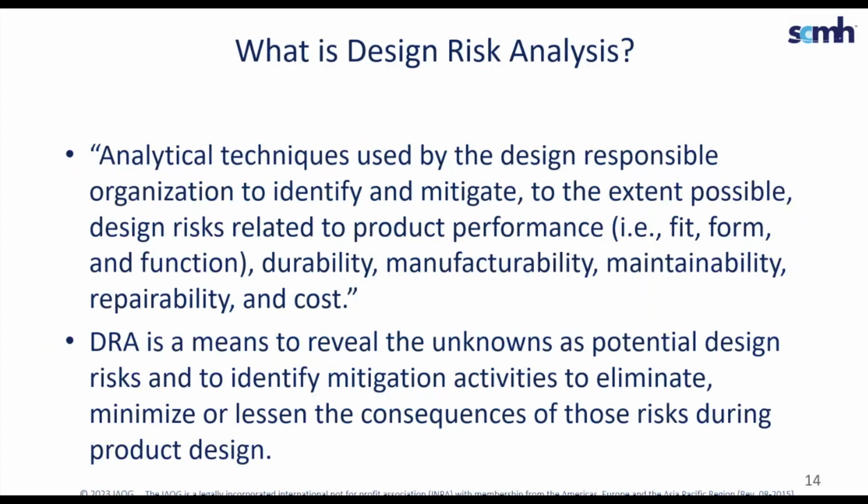Now, I do want to note that the aerospace safety assessment process, and you can reference ARP 4761, is an independent process from DRA. However, the safety assessment process does interact with the DRA process and is a key means of identifying design risks. You have the failure modes, effects, and criticality analysis, or FMECA.